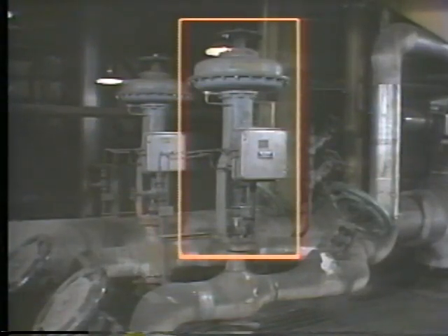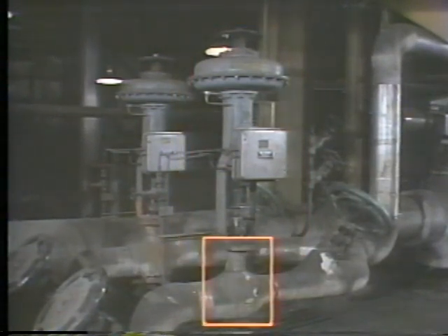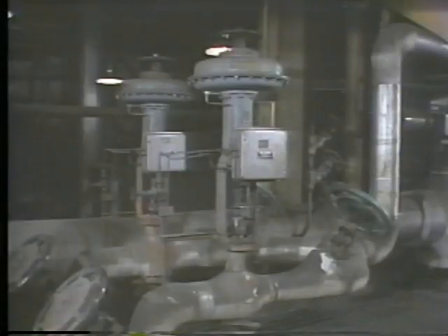The actuator and positioner in this application is used to position a valve that regulates the flow of water in a pipe. The actuator has been mounted on the valve casing, and air from the loader is connected beneath the lower diaphragm casing. So, this is an air-to-lift and spring-to-return diaphragm actuator. Air has been introduced to the diaphragm, so the actuator is in the open position. What needs to be done now is to connect the actuator stem to the valve stem and adjust an indicator plate.